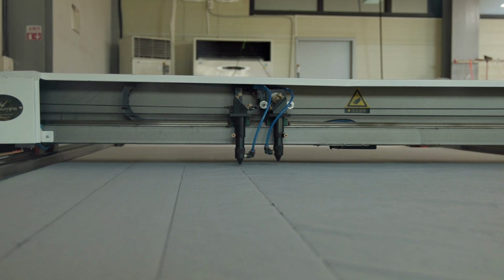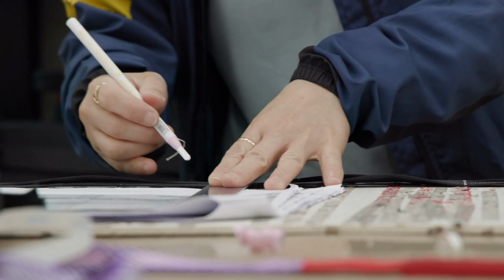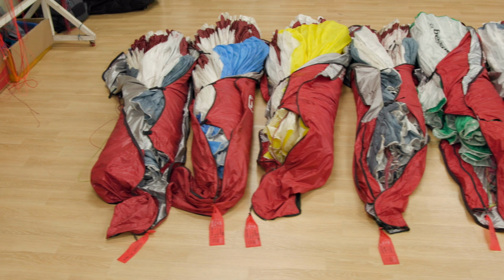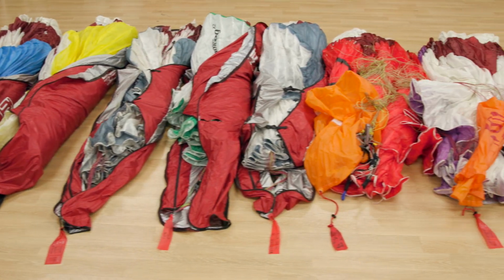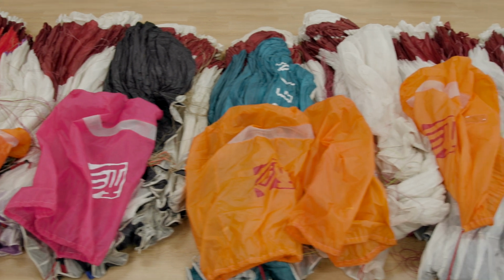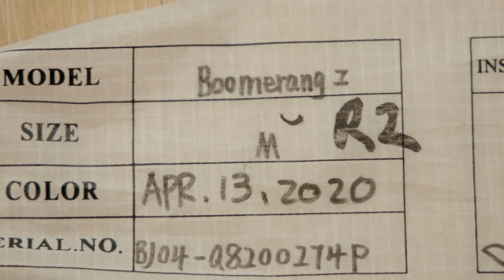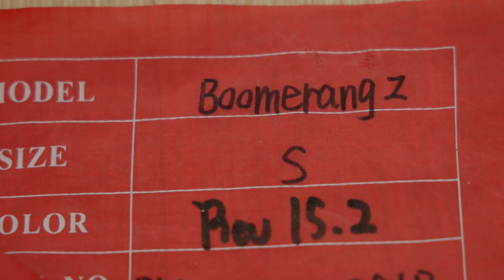The first time we produced the leading edge prototype, the fabric of the leading edge had a kind of bias direction. That's why the tension was different in each panel. We found out that if we twist each panel a little bit to find the right direction, then the wrinkles and leading edge tension were better. I'm not aware of how many prototypes he did, but I know that he made quite a lot. Because it's a brand new concept, the shape of the leading edge and everything was adjusted. It's really not so easy to do.